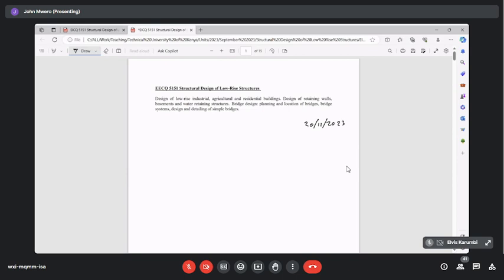Now we know how much the concrete is stretching at the bottom, courtesy of the tension there. So the reinforcement is resisting it, but the reinforcement, because it is stressed, it's also stretching a bit. So with that, and using similar triangles, we've calculated how much the concrete is trying to stretch at the bottommost, because when you bend an element, the bottom becomes under tension and the top under compression. So that's where we are, and now we want to conclude the back calculation.